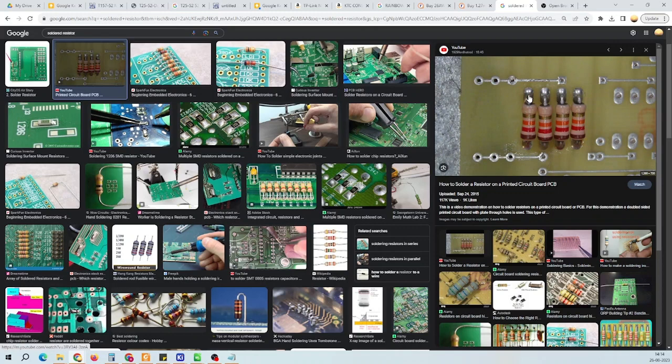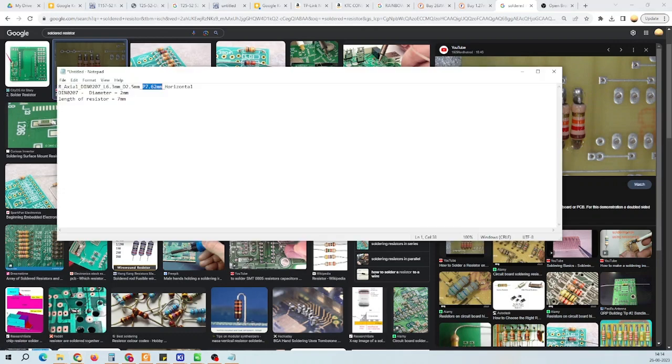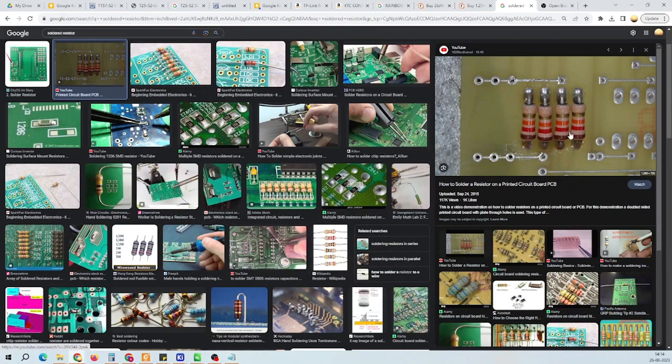And the distance between the soldered points, from this point to this point, is the value that was mentioned here, 7.62 mm. So this is the definition of the value that was given in the footprint option. Pitch is basically the distance between the soldering pads. So ultimately a resistance will be soldered. So this is the distance between the soldering points.